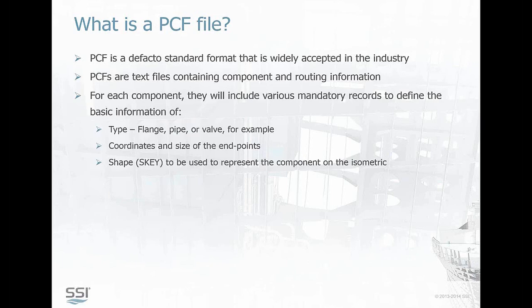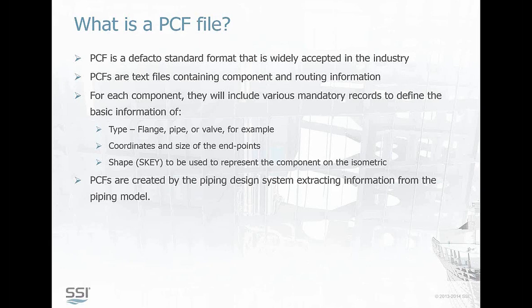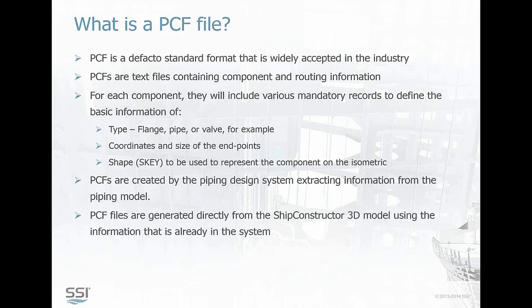For each component, they will include various mandatory records to define the basic information, such as the type of pipe, the flange, pipe, or valve, for example, coordinates and size of the end points, and the S keys. The PCFs are created by the piping design system, extracting information from the piping model, so it actually analyzes the network and outputs that information. It comes directly from the ShipConstructor 3D model using information that's already in the system. So once you're doing your modeling, you can run PipeLink very easily, and we'll see that demonstrated.